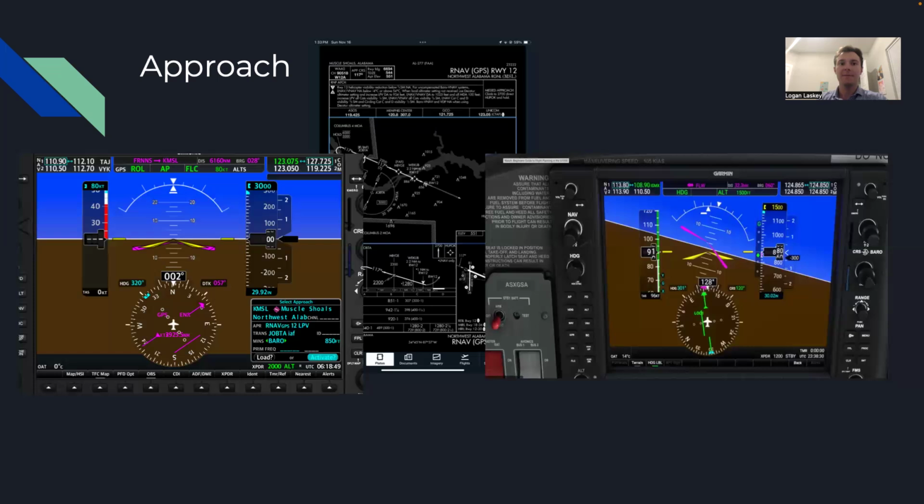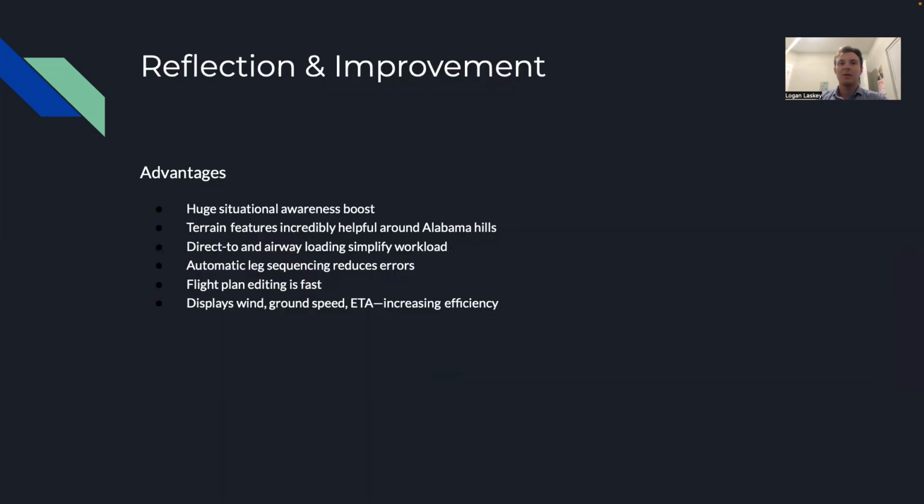We'll hit suspend again. While we're talking about soft keys, if we want to fly GPS or localizer, it will switch over automatically, but what you can do is hit CDI. And then we can squawk with our transponder. Let's say it says squawk 2000 or 1500. You can hit the XPDR and then put in whatever numbers we need. So that's how that'll work.